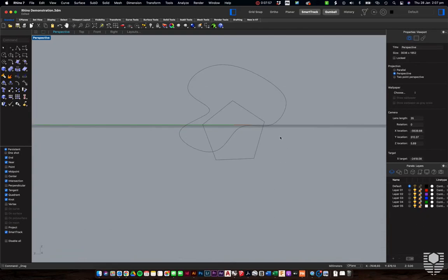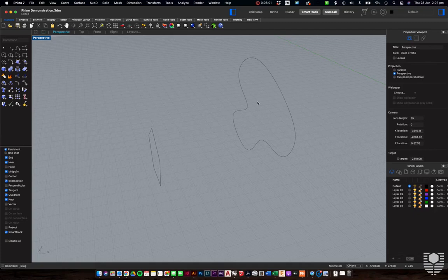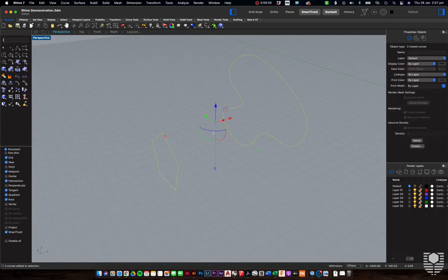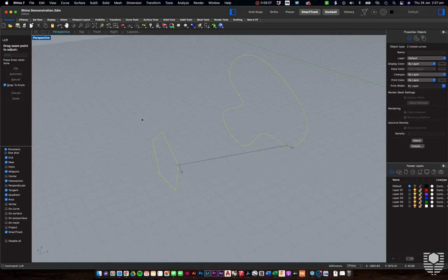Gumball, yes, I want this shooting out to that one. I want to connect these vertices into this curve. Complex thing to do in CAD, not so much in Rhino. All right, so we'll select both of them and then we type in Loft. And then it's going to ask us where we want the seam. I want the seam to be down here. The seam, effectively, if you imagine you're going to 3D print this thing, where does it all join together? So once it all comes back around on itself, it's going to come back to this point. I want the seam to go that way.